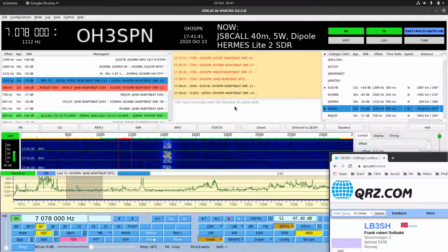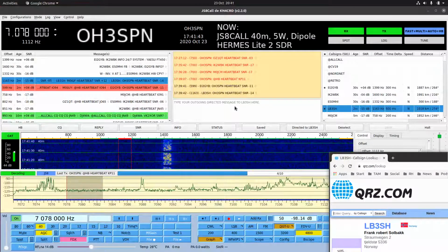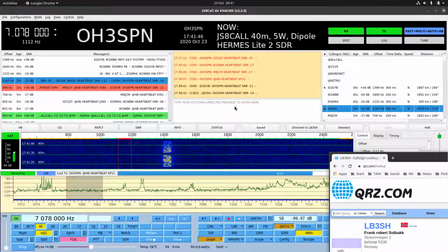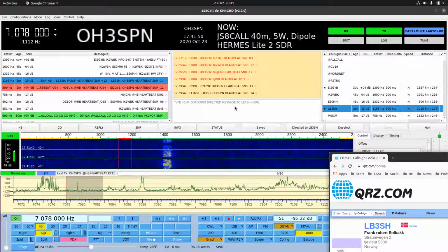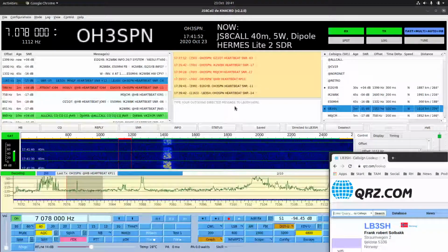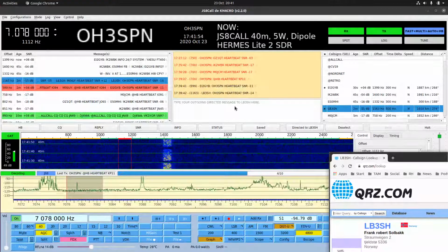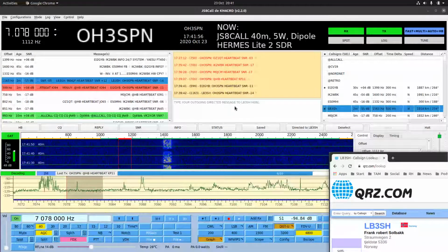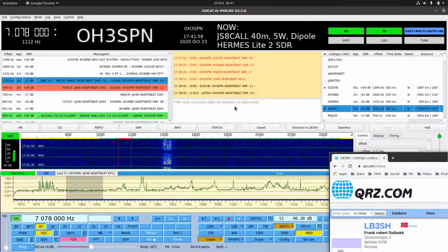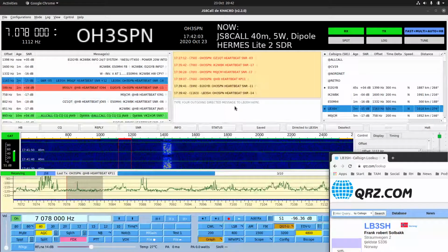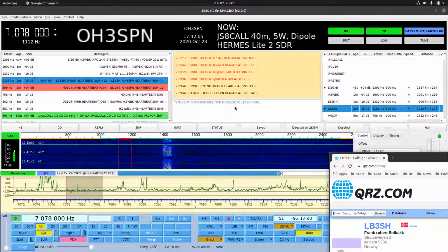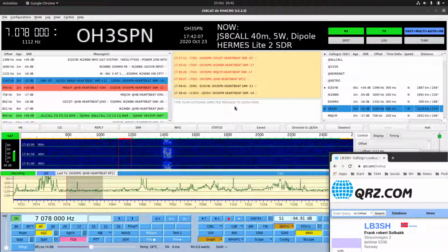I was running the Hermes SDR and about 20 to 30 watts from a home-built, well, Chinese kit that was home-built and modified. The kit cost about €15 and develops about 70 watts output, but with a few modifications to present a better input SWR and low-pass filter to clean up the output.